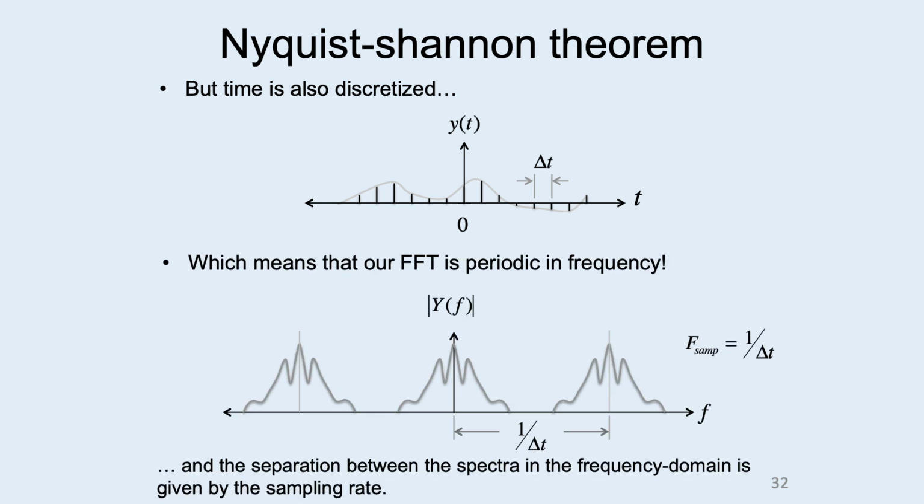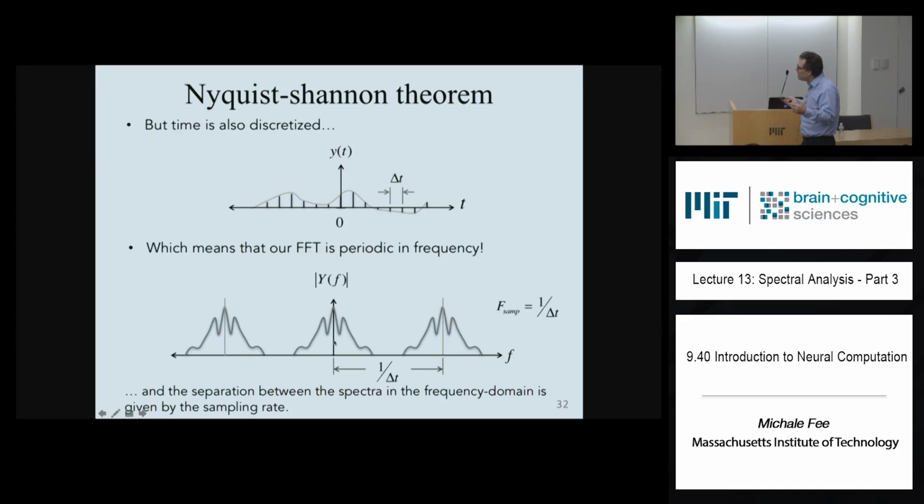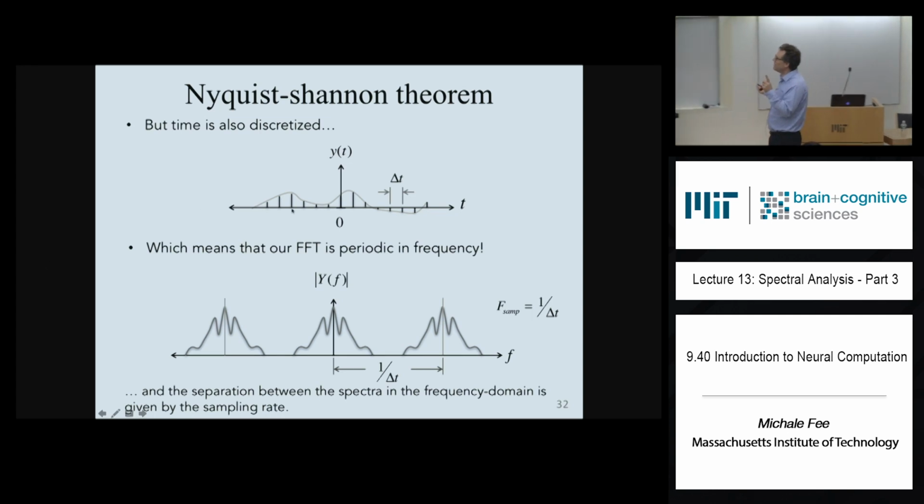So when we pass the FFT algorithm a signal that's discretized in time, it passes us back this thing here, with the positive frequencies in the first half of the vector and the negative frequencies in the second half. It's really one period of a periodic spectrum. Mathematically, if our signal is discretized in time, it means the spectrum is periodic, and the FFT algorithm is passing back one period. And then we do this circular shift to get this thing. That make sense?